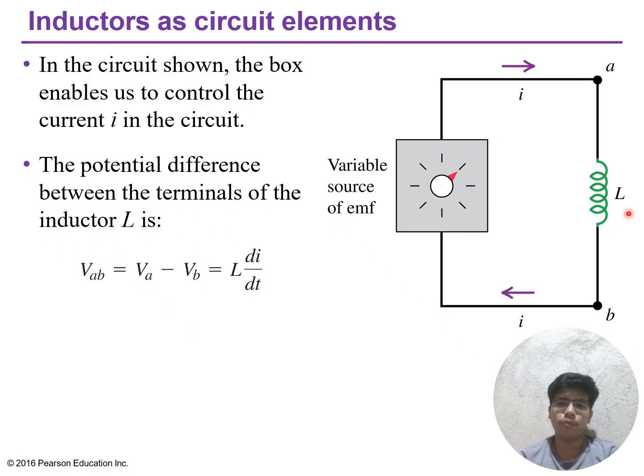So inductors oppose high frequency current more than low frequency or DC currents. This property is used in filters. Inductors block high frequency in low pass filters, and capacitors pass high frequency in high pass filters. The voltage current relationship guides analysis of RL, RC, and complex circuits.